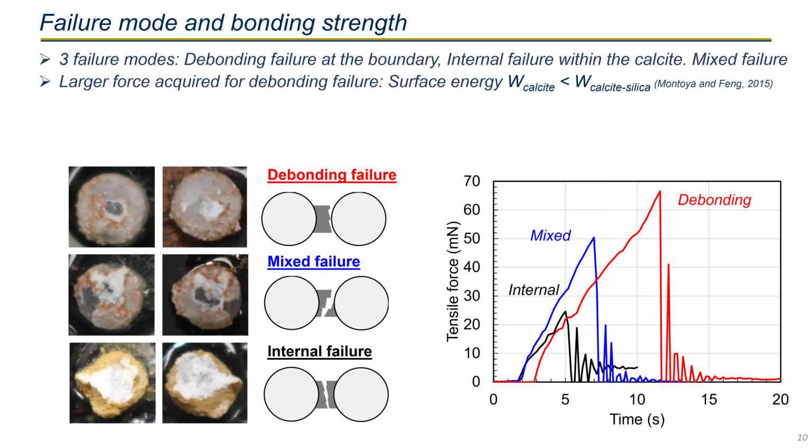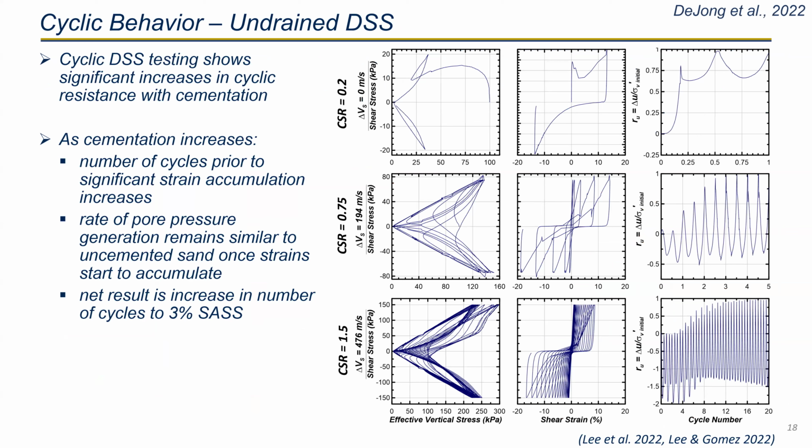Yeah, sounds good. And the part that you were talking about, the simple shear test, you were just presenting the results. Did they study the liquefaction in the simple shear test? It was studying liquefaction, because as I noticed, the shear strain that was recorded was around peak to peak 20%, 30%, which is way more than whatever liquefaction suggests.